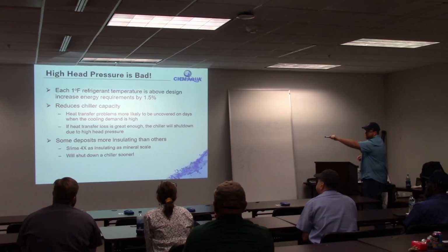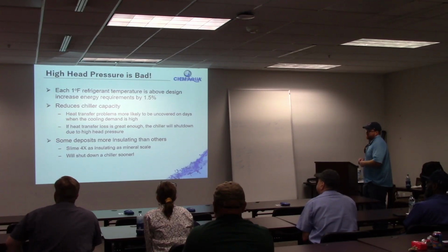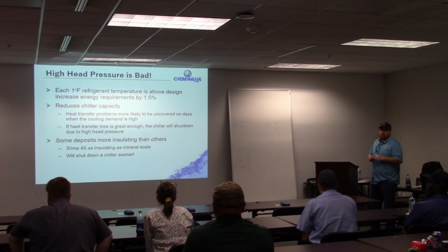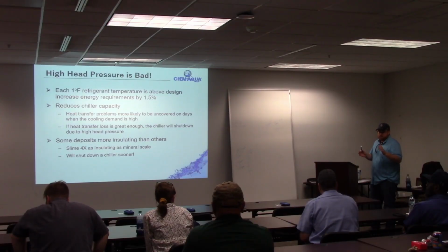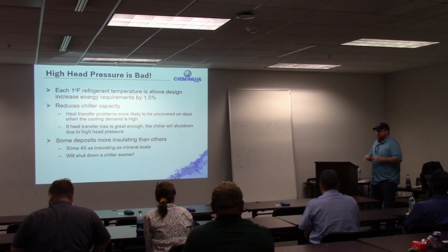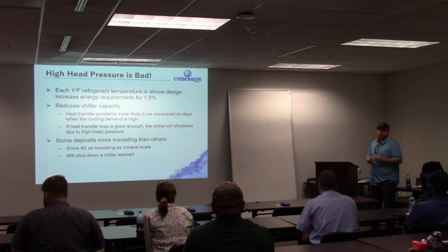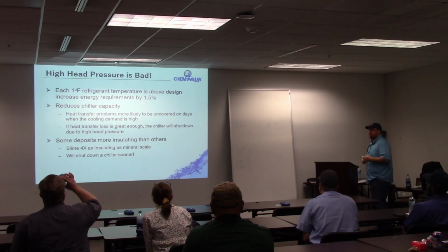And then we talked about this earlier too, down on the bottom, slime is 4 times as insulating as mineral scale. So always be aware of that when you're doing your annual inspections. A lot of times people are opening up chillers just looking for scale. If you're feeling something a little slick and slimy in there, even if it looks clean, that very well could be a bioslime that is causing heat transfer problems that you might not be aware of.